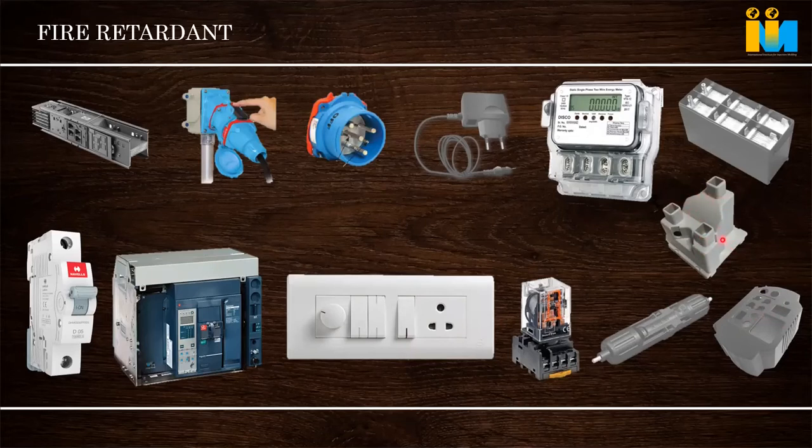This is the back part of an electrical switch. Here some are using polycarbonate fire retardant, or if it goes for higher ampere, suppose this is a 16 ampere switch, polycarbonate is okay for the backside, but if it goes for a 32 ampere socket, where we are putting a heater or geyser, or microwave oven or something, 32 ampere higher current, then polycarbonate is not sufficient. Then we have to go for PBT glass fill. Then only it can go up to 160 degrees of continuous use temperature, and it has more electrical property, and it will not burn away also. This is how material selection has been done.